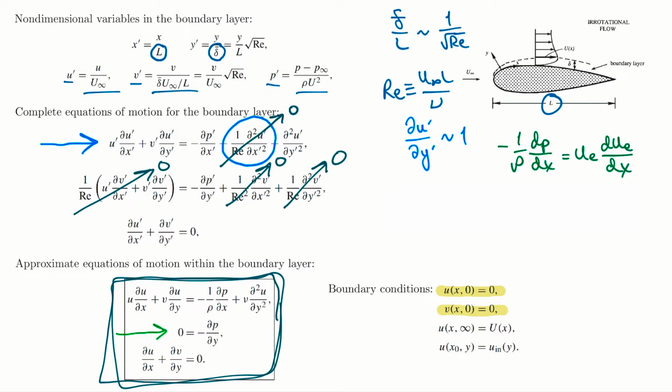We're imposing by this one the fact that the boundary layer must join smoothly with the inviscid outer flow. So points outside the boundary layer are represented by y equals infinity, although essentially we're referring to this non-dimensional distance y over delta, which scales like this here that we've written, and approaches infinity outside the boundary layer. And our final condition that we've listed there implies that we need some initial velocity profile, this u sub in, at some location x naught, to solve this problem.